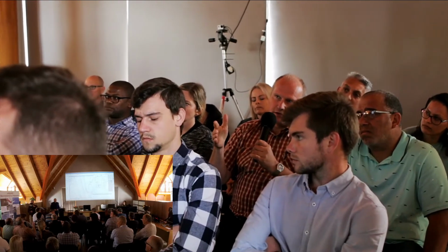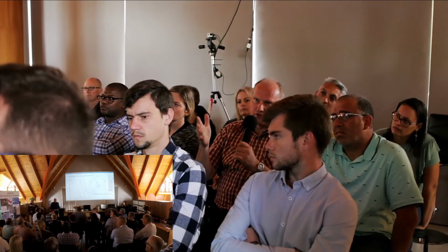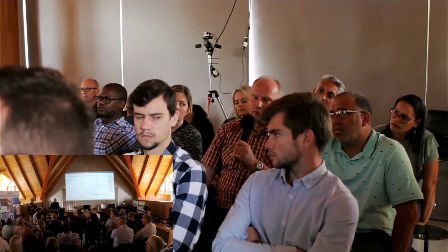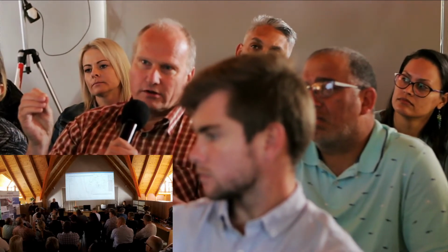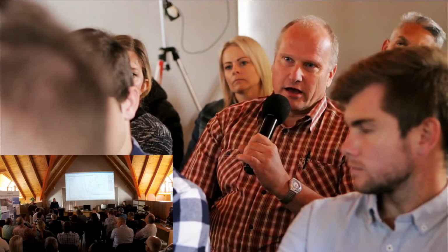Now, in our case in the city, we have a LiDAR point cloud, which is massive. So let's say we've got those 8 billion points, and we generate contours. Then we improve the contours, and we do editing of those contours. So then a month later, we discover that a few points in the LiDAR point cloud have an error, like there's a spike in the data. So we fix the spike and regenerate the contours. Now when we regenerate the contours, we run it overnight, and a day later we have new contours, then we lost all those edits. Now how do we deal with that?